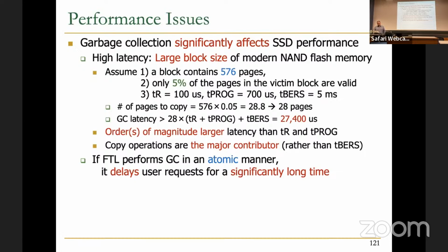So if the FTL performs garbage collection in an atomic manner, like once the FTL starts garbage collection, it does not service anything until things are done, then it can delay user requests for a significantly long time. And that was the case actually for traditional SSDs.